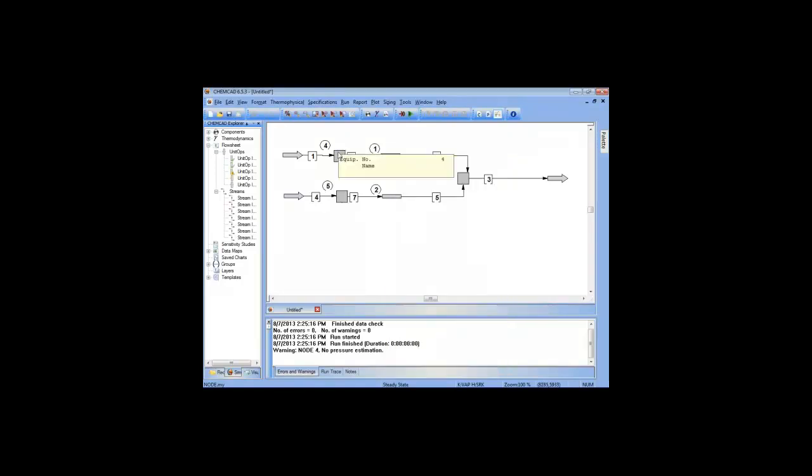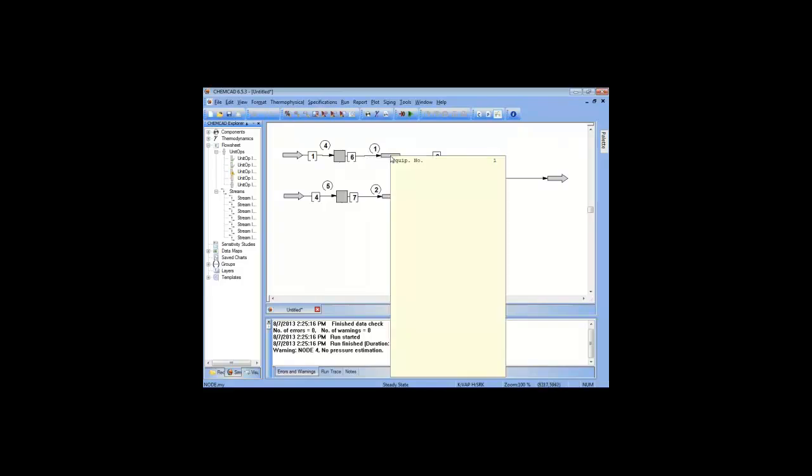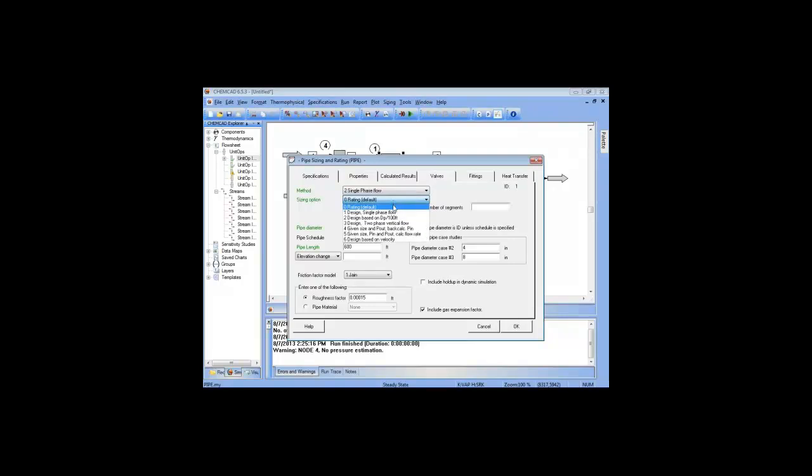So this is going to specify a pressure and calculate a flow rate. We have to change this if we're using it in a flow scale operation to mode 5, which I mentioned earlier that we'll be moving to. Now that we're in mode 5, we're going to be given the pressure, and from the pressures we're going to calculate flow rate.